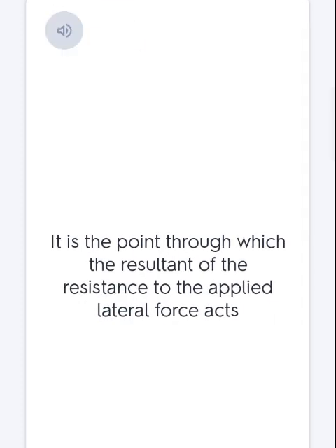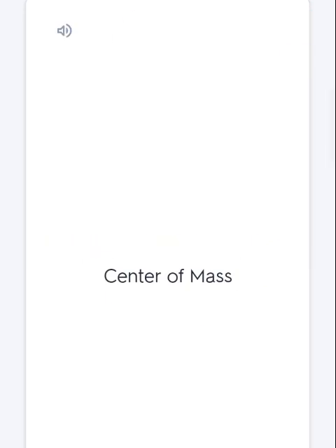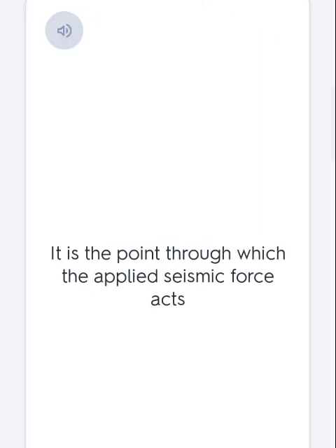Center of rigidity. It is the point through which the resultant of the resistance to the applied lateral force acts. Center of mass. It is the point through which the applied seismic force acts.